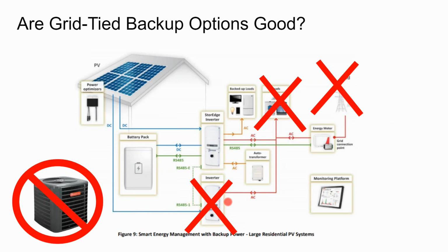That's because if a tree falls over a power line, they don't want the distributed solar inverters backfeeding the grid and electrocuting the linemen who are trying to repair the power lines. And so a safety provision is built into their listing that says, okay, whenever they see a grid signal, it'll take the inverter 5 minutes to turn on so that the linemen and repairmen can get their work done in a safe and effective manner.